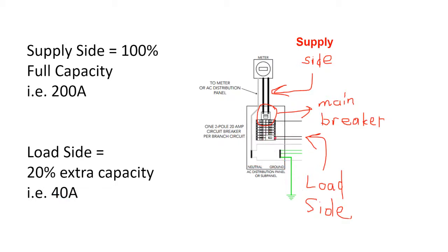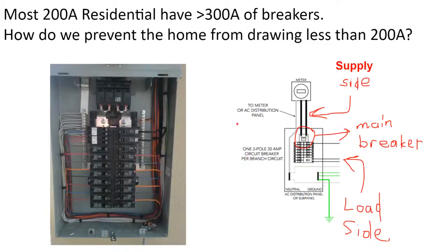As a starting point, National Electric Code dictates a 200 amp electric service cannot be fed with more than 200 amps of power, whether it comes from the utility through the main breaker or from the solar array through a load side breaker or any combination thereof. In other words, if a 200 amp service panel has a 200 amp main breaker, then it has 0 amps available for a solar load side connection.